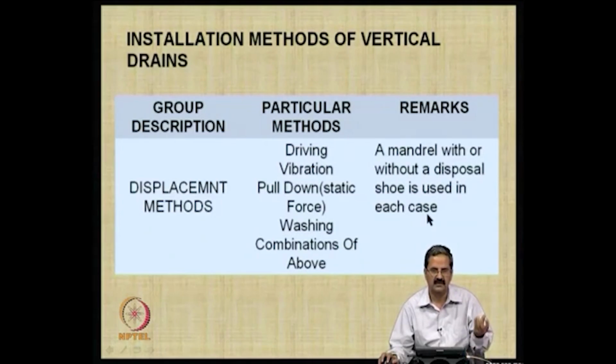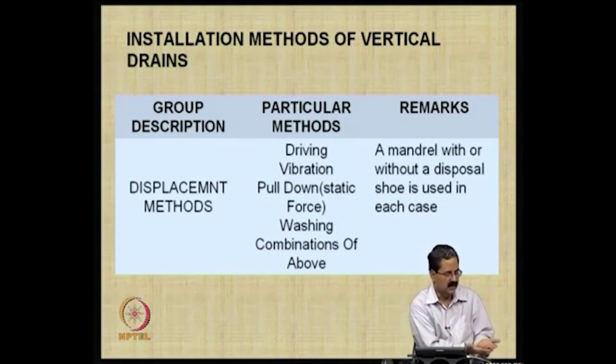Like I showed you in one of the earlier photos, where you have a simple shoe and it reaches the required depth. Once you want to remove it, it opens up like that, so it stays there. That is a very interesting thing: you put it in, and when it tries to withdraw, it opens up and forms a shoe at the bottom, at whatever the required depth is. Then when you try to pull it back, it will not come, because there is some force preventing it. So once you realize that, you cut it.